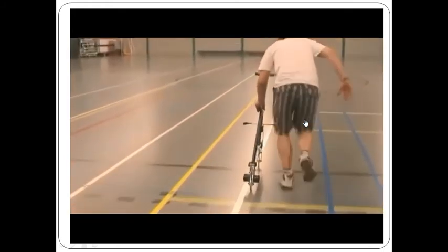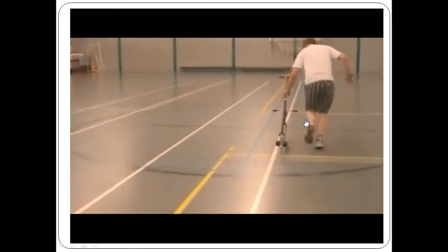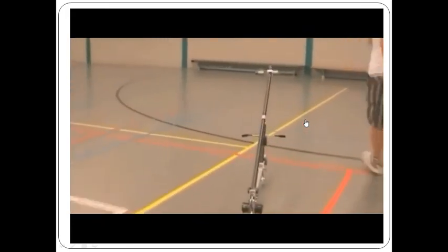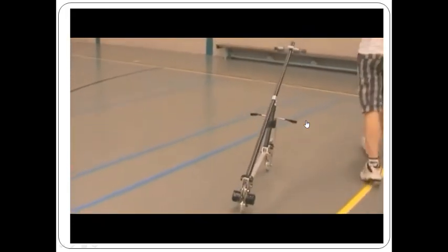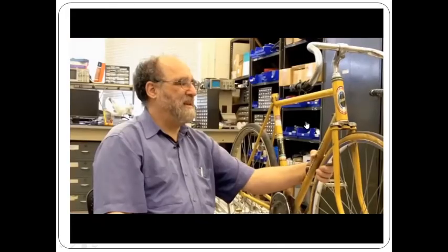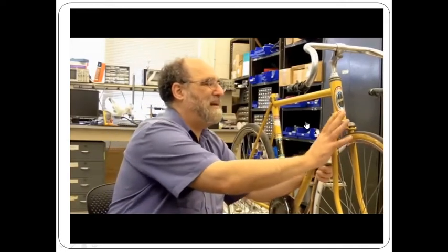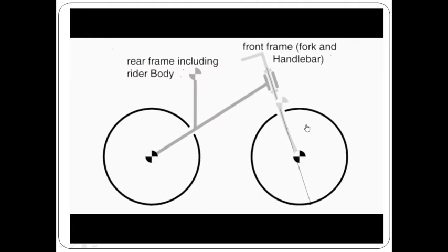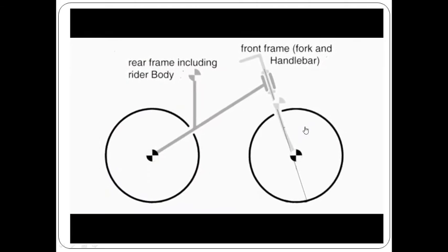But there are various mechanical effects besides the gyroscopic effect and besides the caster effect where leaning can cause steering. And the mechanism that the bicycle has for being self-stable is that it has a mass in the front assembly which is forward of the steering axis, and it has a mass in the frame.